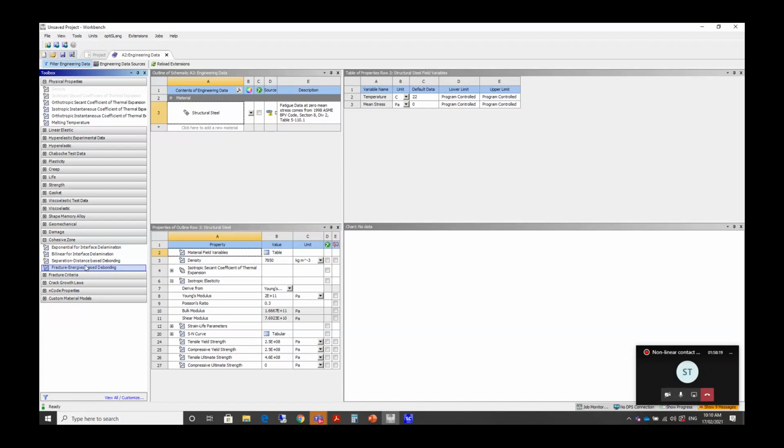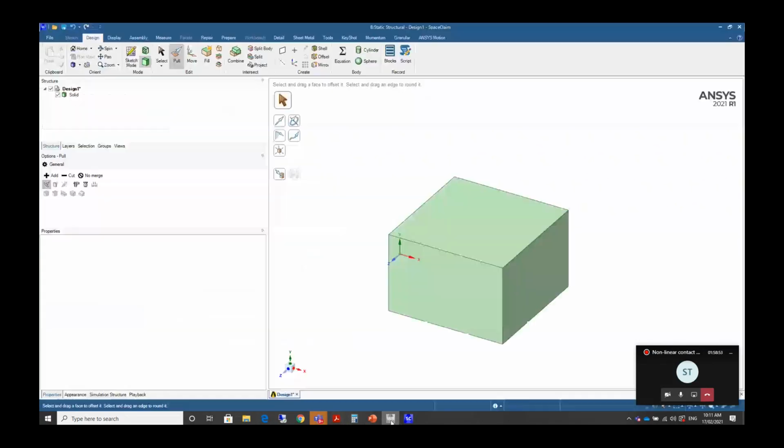Okay, so here you can do different properties. You can do fracture energy based debonding, or separation distance based debonding. If you look in the help, it explains what parameters you need to put in, and sometimes you need to fine tune these parameters to get close to reality. Okay, so I won't worry about doing that bolt thread.